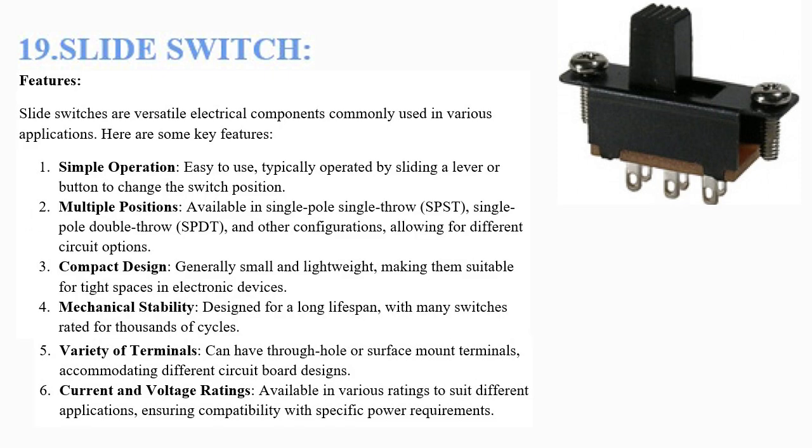Features. Slide switches are versatile electrical components commonly used in various applications. Here are some key features. Simple operation, easy to use, typically operated by sliding a lever or maybe a button. Multiple positions, available in single pole single throw or single pole double throw. Compact size, generally small and lightweight, making them suitable for tight spaces in electronic devices. Mechanical stability, designed for long lifespan with many switches rated for thousands of cycles. Variety of terminals, including through-hole and surface mount terminals, accommodating different circuit board designs.